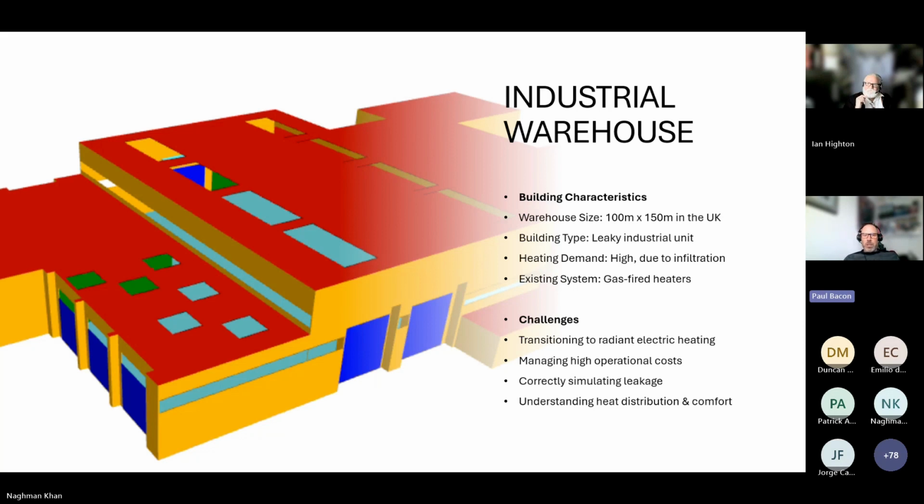So the first thing they wanted us to do was some energy calculations for them. They had all of the measured data for the energy, which was very useful in this case. When we set up the model, like you normally would for a building of this age and those sort of constructions, it was nowhere near. It soon became apparent that it was purely down to the leakage of the building, the infiltration. So we modeled the infiltration in much more detail than you would normally. We didn't just put a blanket air changes per hour in there; we actually modeled the crackage. Then we managed to start marrying up with the actual recorded energy figures that they had measured on site.